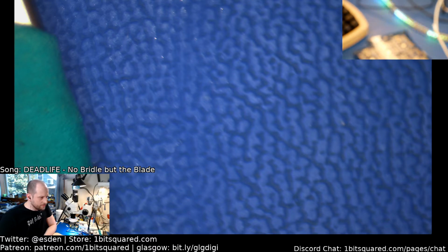And now there is another feature in here, which is manufacturing or fab notes for the PCB manufacturer. In some cases they read it, in other cases they don't. It really depends on the manufacturer, especially if it is a quick turnaround, cheapo manufacturer. They definitely don't look at this. They're like, I don't care, I will do my magic on the board. They screw up your board so that it can quickly go on their etching machines, then you get some board and it might work. That's usually what you get from JLC PCB.